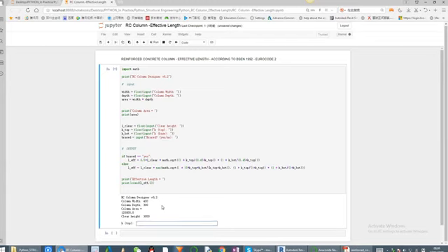The value of K2 is 0.096, as we've seen before. The value of K1 is equal, because it's a symmetrical frame, as I said. Is it braced or unbraced? We decided to design as a braced member, so I'll type yes. So we get the value of effective length equal to 1.777, which you can round up.